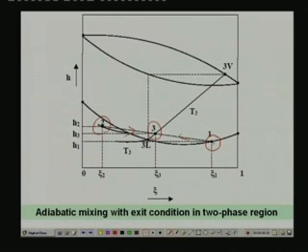So, when you are plotting it on this, knowing m1 and m2, and if you find that this point lies in the two phase region, then we do not know this temperature. And two phase region means again it will have vapor and liquid phase mass fractions. Again this temperature as well as vapor and liquid phase mass fractions have got to be obtained from trial and error method, as I have explained earlier.